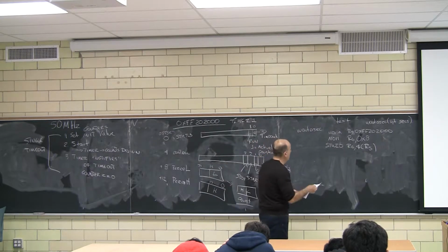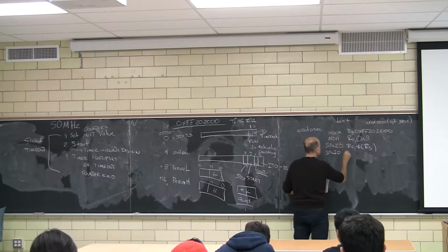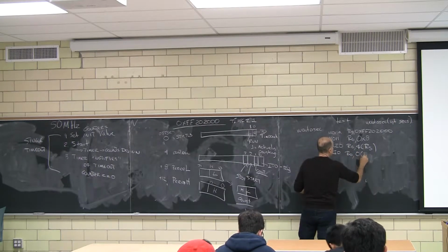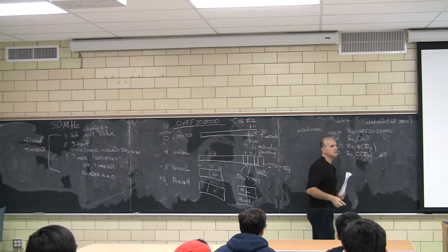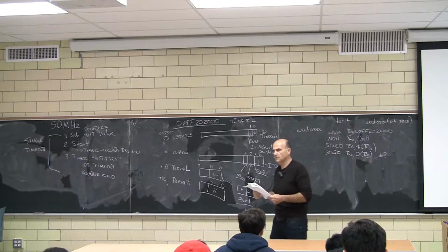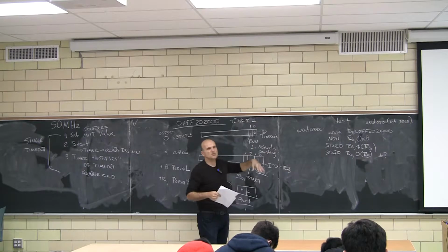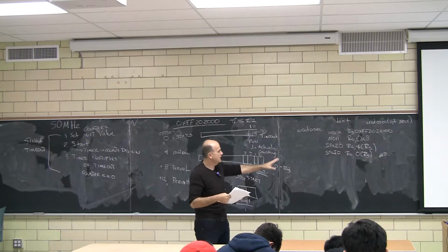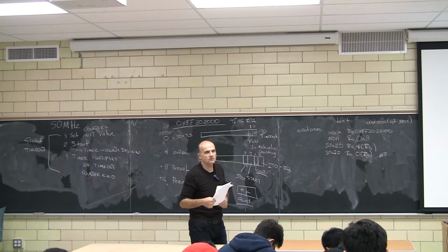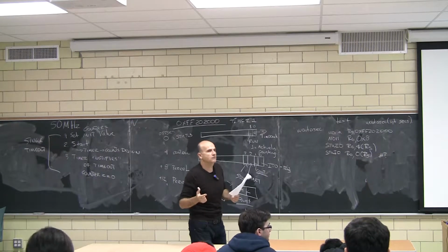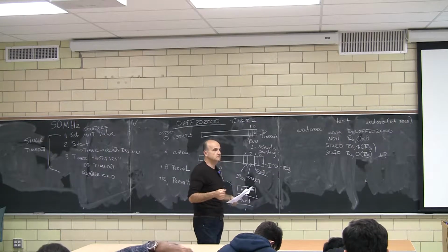Okay. Now, I don't know whether that's really needed, but how about we do a store word IO R0 0 R5. Again, for this one, please double check it in the lab whether you actually need that or not. I don't remember at the moment. This also clears the intention here is to clear the timeout flag. But I think stop does that anyhow. So that's why I have this in question mark. If the TAs give you a hard time if you put this in your lab, just say, my professor Andreas said so, blame him. Okay? So far so good?